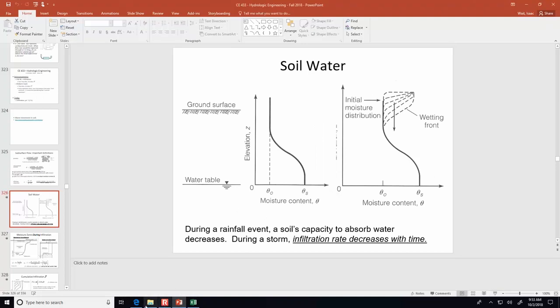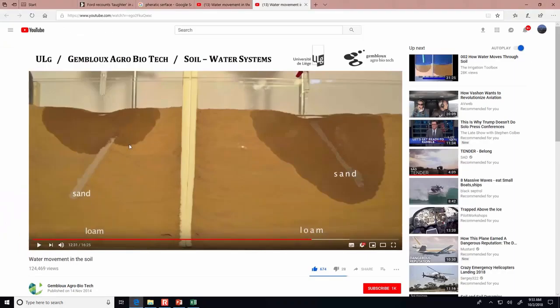And that's what we're seeing in this video, is we're saying that it may be saturated at this point, but this isn't fully saturated. If it was, it would be penetrating through the sand, because we see what happens when the voids are fully saturated. The sand immediately becomes like a highway for that water to pass through, because it has such a high hydraulic conductivity. So that hydraulic conductivity effect doesn't kick in until saturated conditions. So I just wanted to pause. We'll continue finishing the video there.